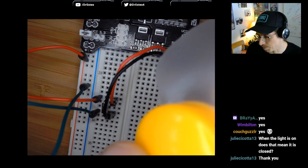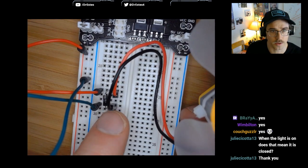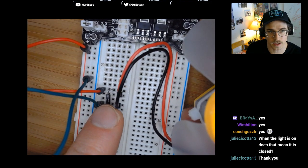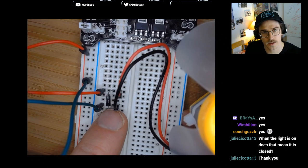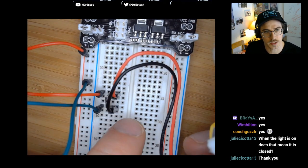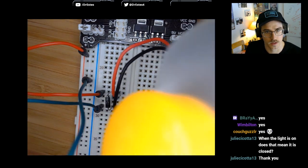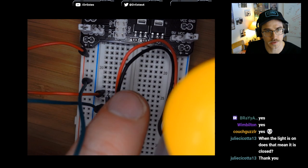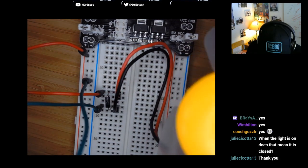It can create sparks and stuff. And a diode essentially prevents that from happening. So you could call it a flyback diode because instead of the voltage spike occurring, current just loops through the motor, through the diode, and it kind of goes in this loop until the energy dissipates.